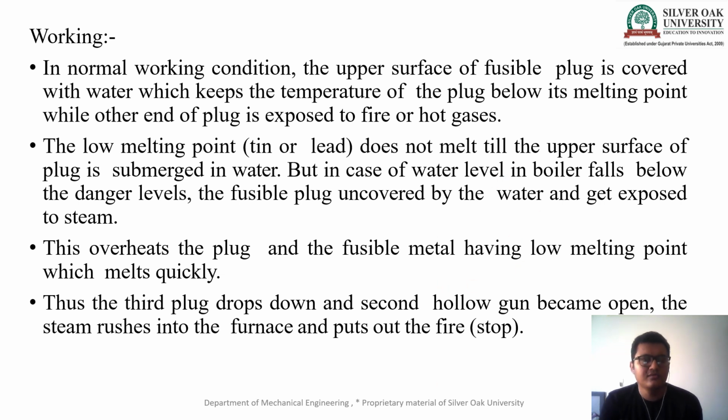Now the working of the fusible plug. In normal working condition, the upper surface of the fusible plug is covered by water, which keeps the temperature of the plug below the melting point, while the other end of the plug is exposed to the fire or hot gases.